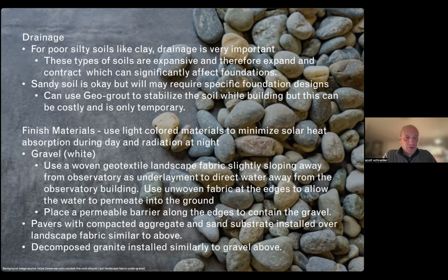Usually you want to put a landscape fabric underneath there. Underneath the building you'd want to use more of a woven type of fabric. You slope that fabric and then you place the gravel over it, and then the water will slope away from the building.